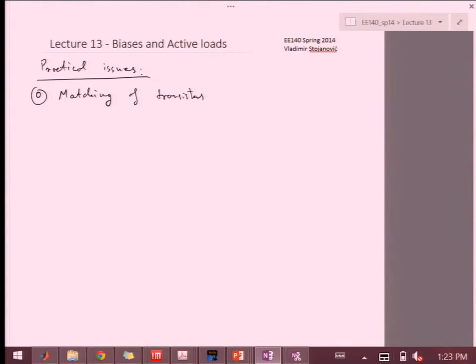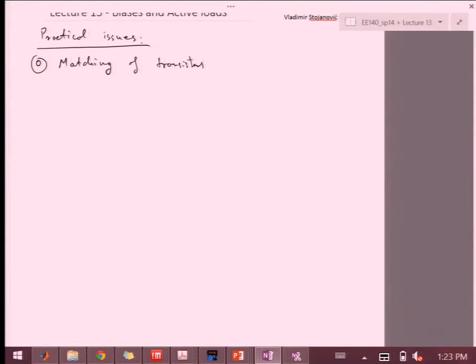And it's useful, in the book they go through a bit more of a derivation, but I'll just jot down the formula here for you. If I have two devices, one is here, and obviously in the mirror, one will be somewhere else. So I'm looking at these two identical devices that have W over L nominal sizes.